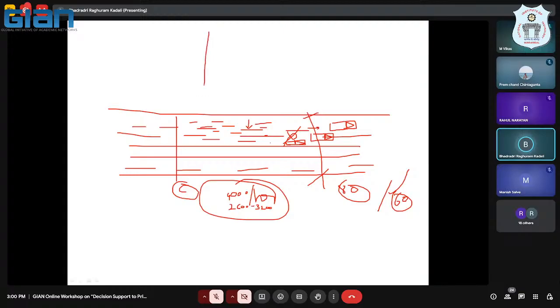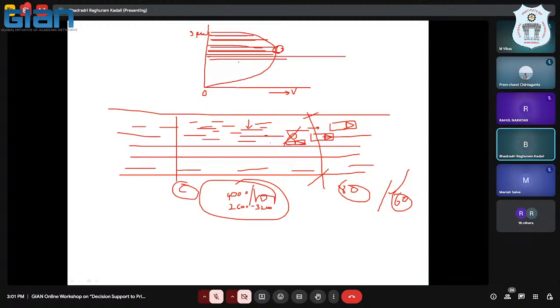So there is a speed-volume relation. This is the speed, and these are the volumes. As the volumes increase, you achieve some specified speeds. If you have zero volumes, then you have the highest speed; as you keep adding volumes, the speed decreases. At some point you don't have any flow, and then obviously it is a completely jammed case. Okay, so that is the way.